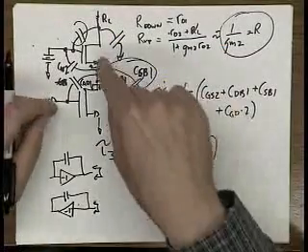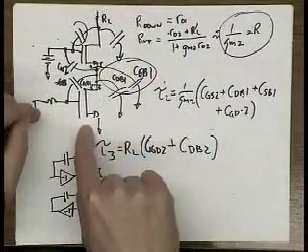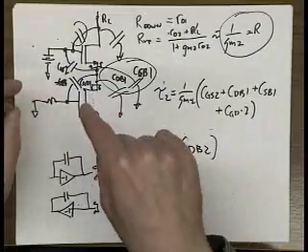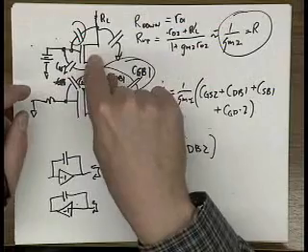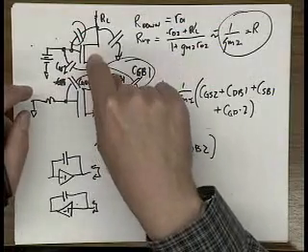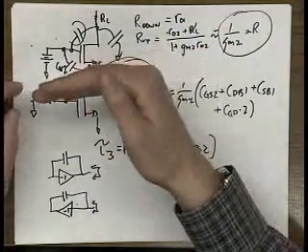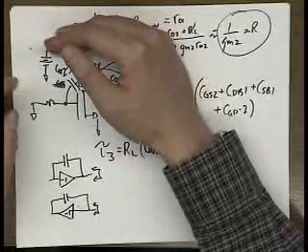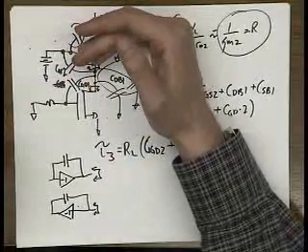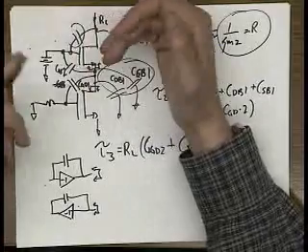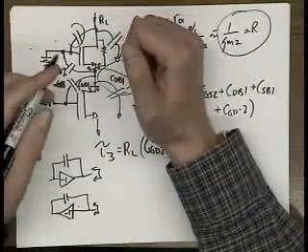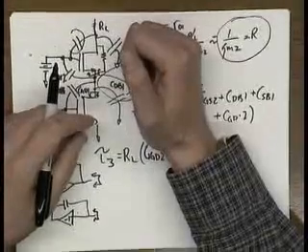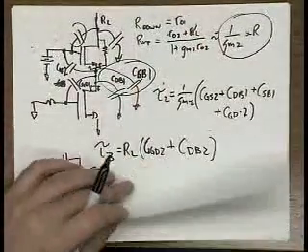And that's the beauty, because a Cascode amplifier is a two-stage amplifier. It's a common source stage followed by a common gate stage. And the great thing about common gate stages is that you do have true isolation between the input and the output, or almost like very good isolation between the input and the output. The only communication is through R0, which isn't frequency dependent. Okay? So that's that.